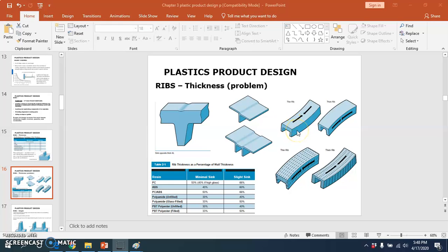In this situation, the end of the rib surface may warp towards the opposite wall. It curves. As rib thickness approaches the wall thickness, this type of warpage generally decreases. However, ribs that are the same thickness as the wall may develop a warp towards the rib side. To prevent this warpage, design extra cooling on the rib side to compensate for the added heat load from the ribs.